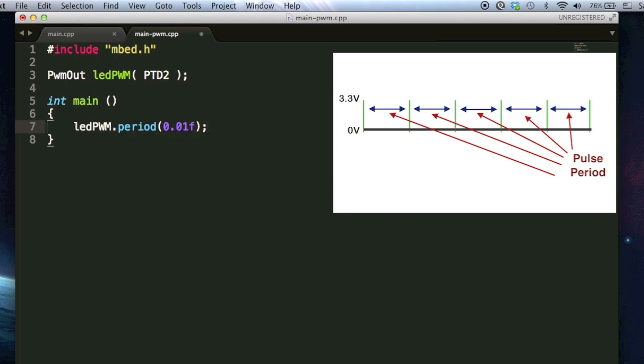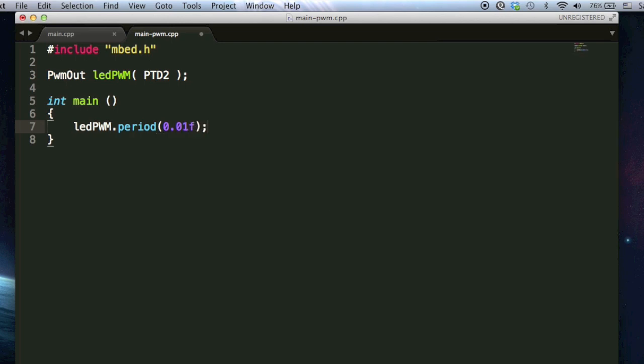The reason why we're doing this is because we're not going to use any smoothing filter on the other end of the digital output. We are just going to do raw PWM on the LED. But your eyes will naturally smooth what it's seeing between the high and low parts of the cycle. So if we cycle it fast enough, your eye will create the intermediate value, even though all we're doing is having it just go on or off for the LED.